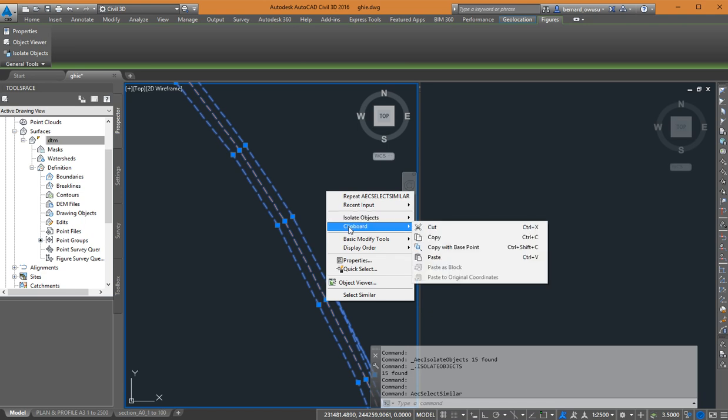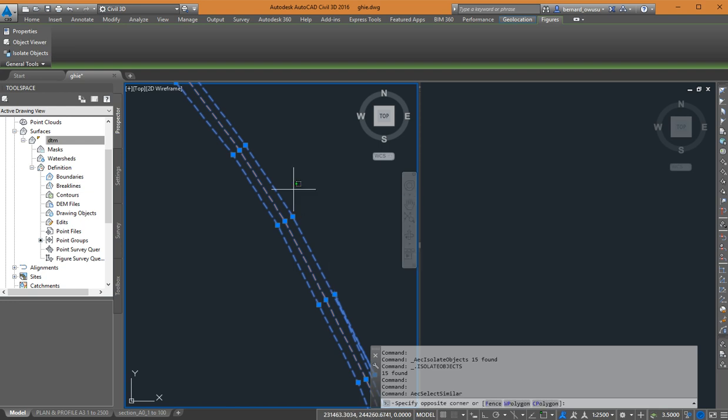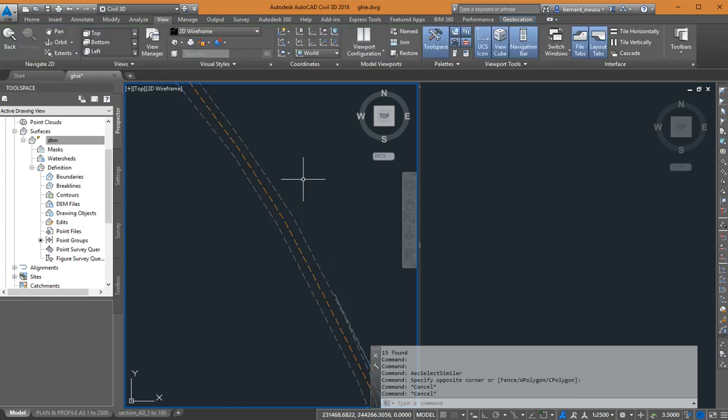Select just the line, the edges. Select the road edges and the center line. Maybe you have selected something more than that. The center line and the road edges. Then right click, select similar. Successful. Please, can we continue? Amma, successful. Okay, so you have only the edges and the center line showing. The rest are all hidden.